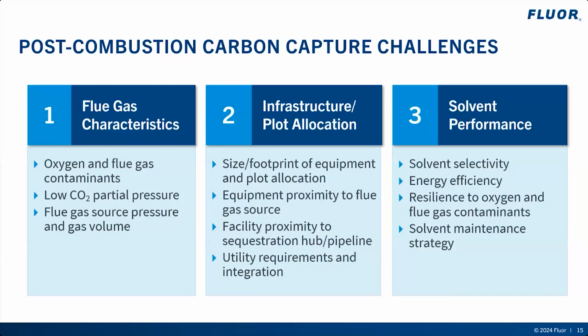Heat-stable salts generated by reactions between the solvent and flue gas contaminants, as well as degradation products from the solvent breakdown, can lead to solvent performance issues, increased corrosion and fouling of the unit, and increased emissions of ammonia and VOCs. The solvent formulation will need to be resilient to degradation in order to maintain this performance.